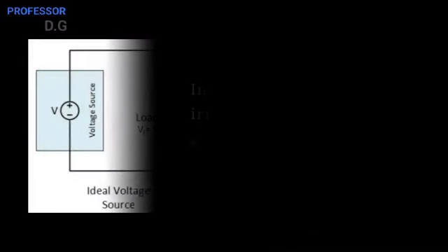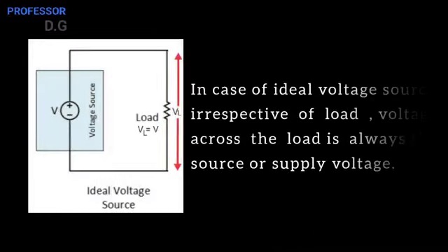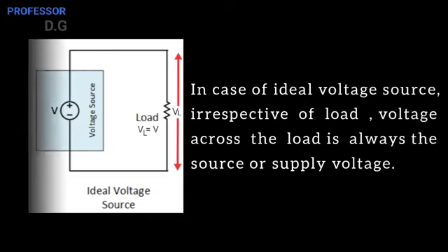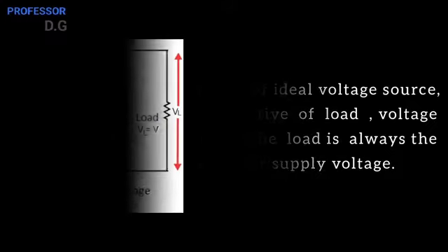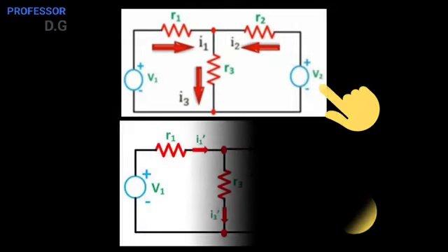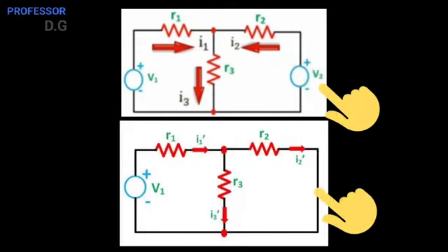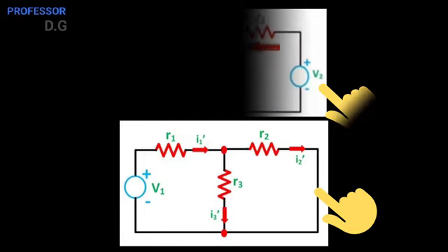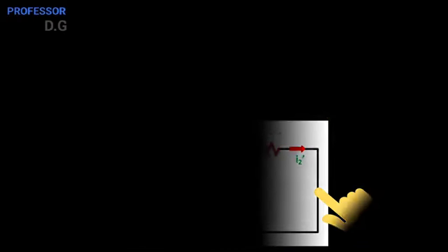In that case, we will consider that voltage source as an ideal voltage source. So, whenever any ideal voltage source is of concern, at that time this voltage source is replaced by its internal resistance, that is zero resistance, and that zero resistance is possible only when the branch is short circuited.